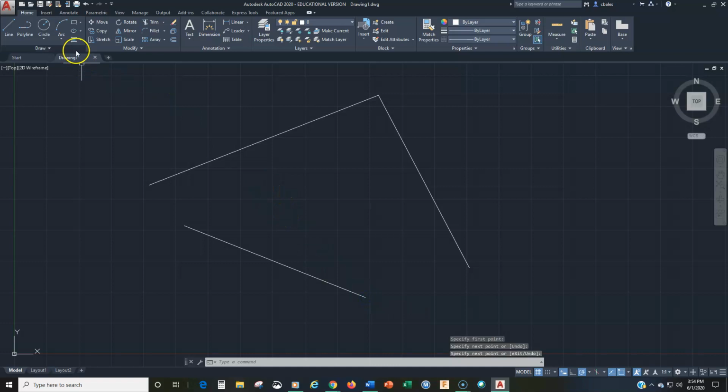Okay, and if I go to the offset command, now I want to take my time here to go through, and I want you to do the same, to go through and make sure that you see what AutoCAD is asking you on the screen. So when I click the offset command, first thing AutoCAD asks is to specify an offset distance. So in order to make a parallel copy of, in this case, let's say this line, we need to know how far the copy is going to be off of the original. Right? What is that distance? So that's what AutoCAD is asking for.